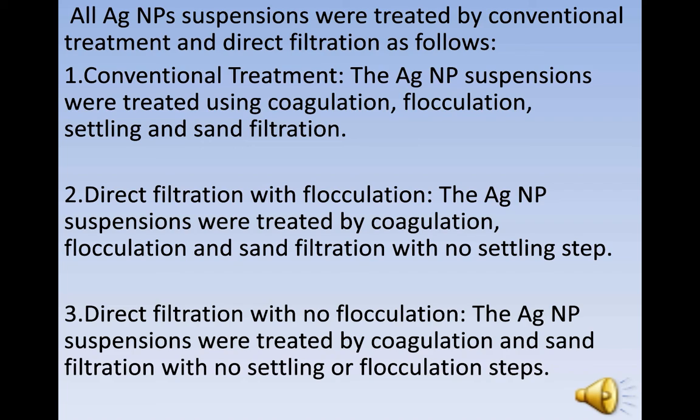The difference between method one and method two is that conventional treatment uses coagulation and flocculation, settling and sand filtration, but direct filtration is without the settling step. The third method is direct filtration with no flocculation, using coagulation and sand filtration without settling or flocculation step.